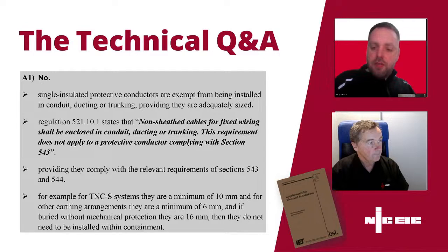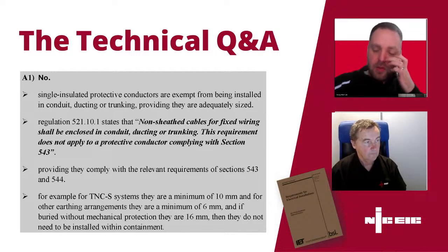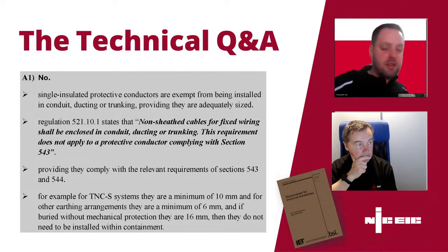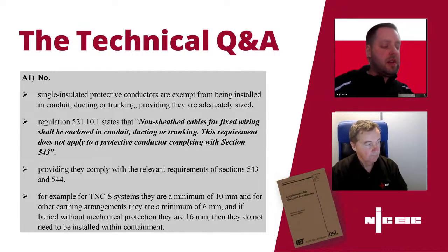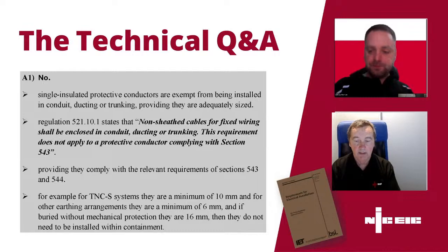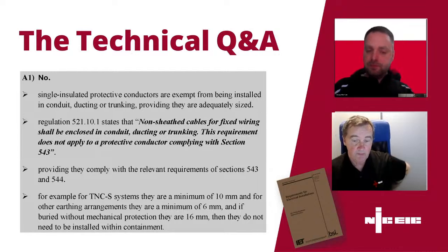Not really, no. I think it's good that the regulation specifically omits them, or clarifies it's not applying to them. Just generally, they need to be suitable for their external influences. I suppose if they were in a harsh environment with heavy impact, then general requirements might apply, but nothing specific in the way that it would be for live conductors being enclosed. Yeah, that's a good point, in that even though they don't need to be in containment, they still need to be suitable for the environment that they're installed in. That's a really cracking point.